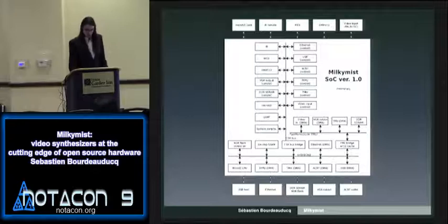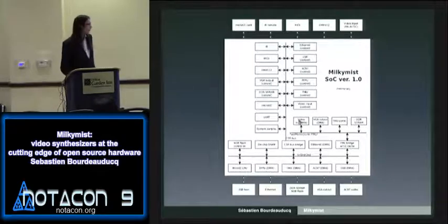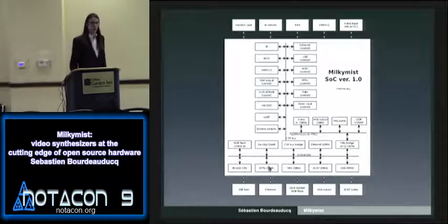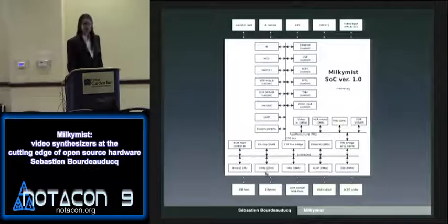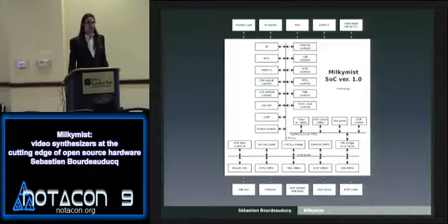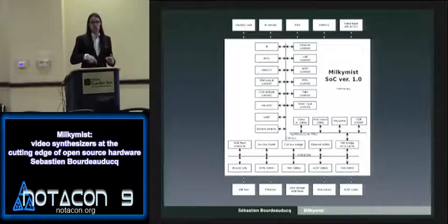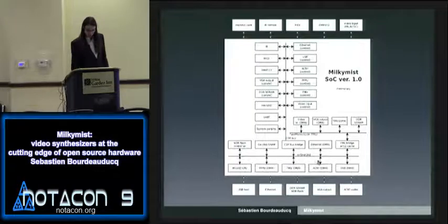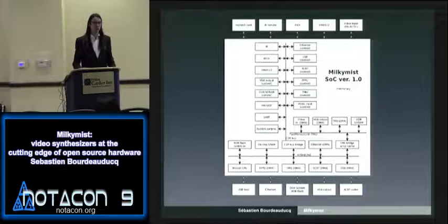So except for a processor and I/O peripherals, we have some accelerators. We have an accelerator here called the PFPU, Programmable Floating Point Unit. It's basically something analogous to a vertex shader that you have in graphics cards. So what it does is you put in a set of equations and it evaluates them very fast. And the TMU is basically a graphics pipeline. It's a 2D graphics pipeline with some other restrictions.